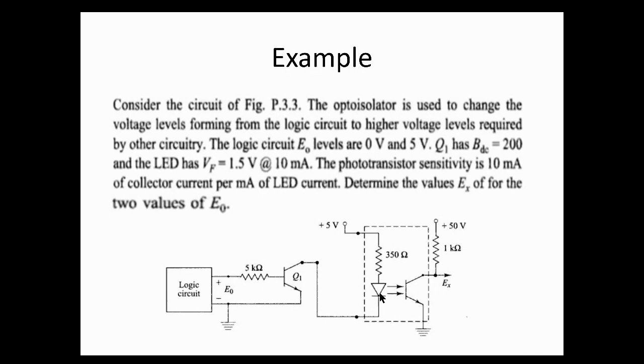Remember earlier on, I mentioned to you that the manufacturer would let you know the specification as it relates to the voltage that is required to switch this LED on, right? So you can now know whether or not, based on the output voltage from your microcontroller, it's going to be sufficient to switch this opto isolator on, right? So in this case, we can work that out quickly.